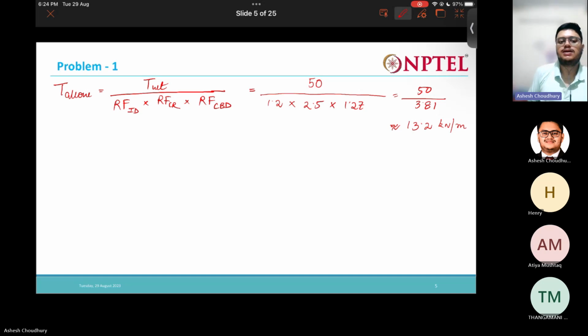We will be designing the spacing in such a way. Now, if you remember, what was the load coming on each reinforcement? That was K, the earth pressure coefficient, times the vertical pressure, which gives you the horizontal pressure, times the spacing.